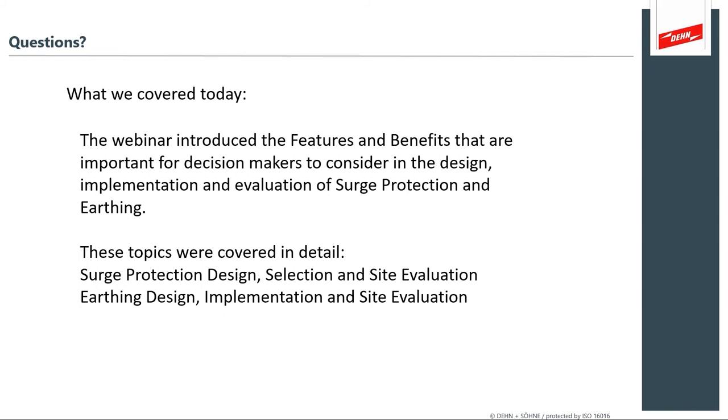Okay, great. Next question: why is it necessary to bond the door when the door is hanging from a metal hinge? Well, the metal hinge is essentially a casual contact. And as you'll see, especially when you have things like lights and instrumentation on that door, if the light socket breaks, you're now injecting fault current into the door, and you don't want to rely on the hinge as your electrical path.